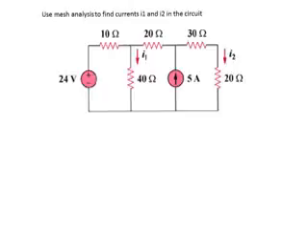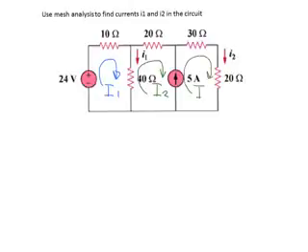And as always, we start in mesh analysis by assigning the mesh currents. We can see that there are 3 meshes in the circuit. Let's call them the first mesh with the mesh current I1, the second mesh with the mesh current I2, and the mesh number 3 with the mesh current I3. To make everything convenient, we'll make the mesh currents go in the clockwise direction.